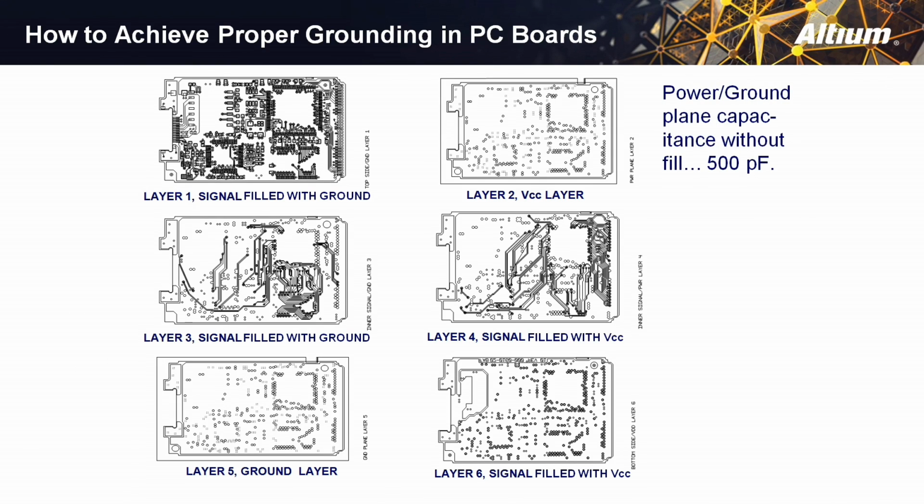In doing so, the measured capacitance of this board before adding the copper pours was only about 500 picofarads. The measured capacitance after the power pours was 4,100 picofarads. And that helped improve power delivery by offering some capacitance that was capable of delivering high frequency energy to the ICs. But the reality is 4,000 picofarads of capacitance is just not very much capacitance compared to the discretes we put on the board.